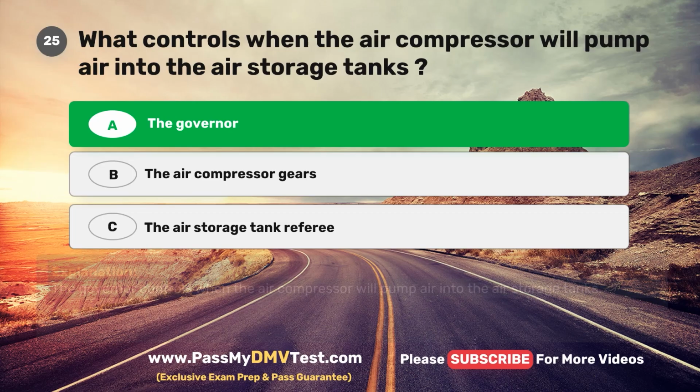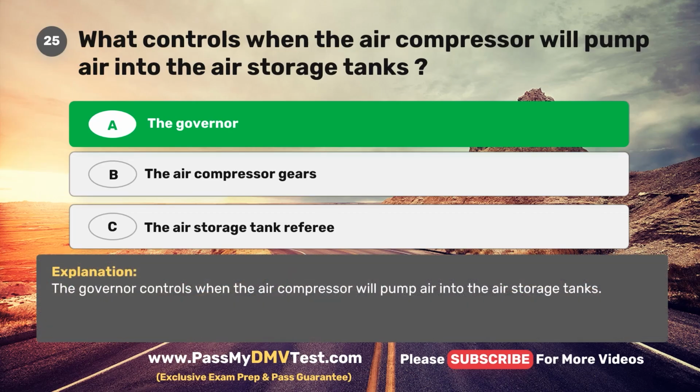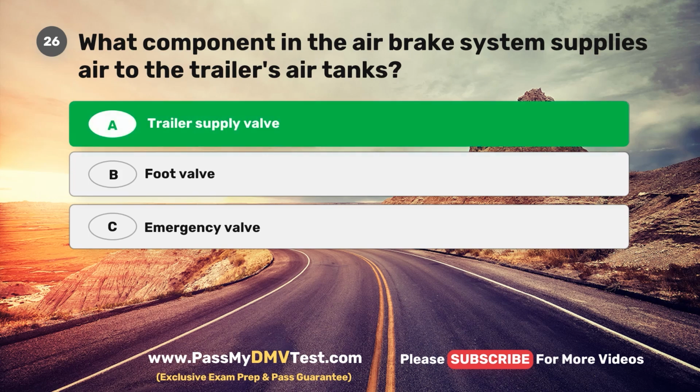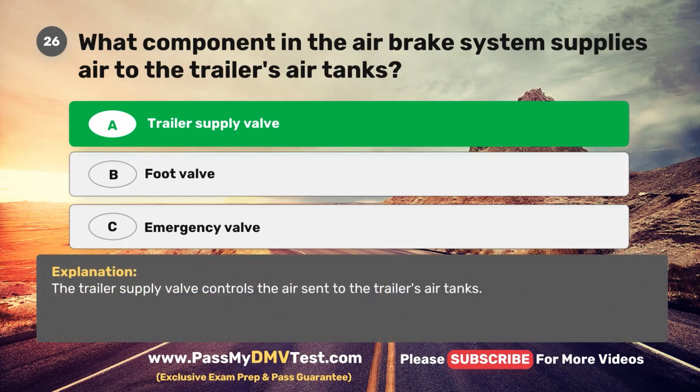The governor. The governor controls when the air compressor will pump air into the air storage tanks. Question 26. What component in the air brake system supplies air to the trailer's air tanks? A. Trailer supply valve. B. Foot valve. C. Emergency valve. The correct answer is A. Trailer supply valve. The trailer supply valve controls the air sent to the trailer's air tanks.